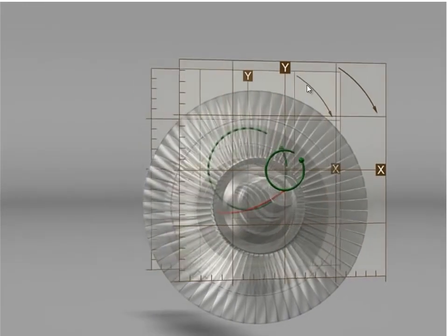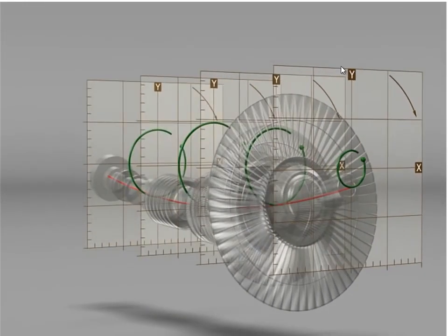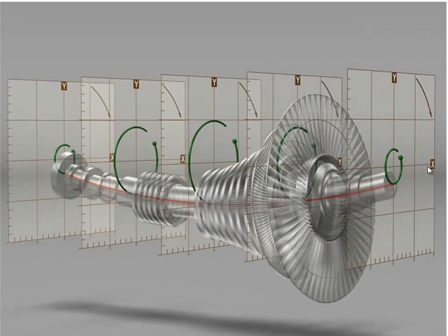And we plot that on a graph, as you can see here, y being the top, x being the side. There are so many details I'm leaving out, but just to give you a general idea, the orbit tells us what the center of the shaft is doing. So here we see this nice little orbit because it's moving in this small circular motion. More here, much more there, less and less, sort of similar, because that's what the shaft is doing, that's what the rotor is doing.